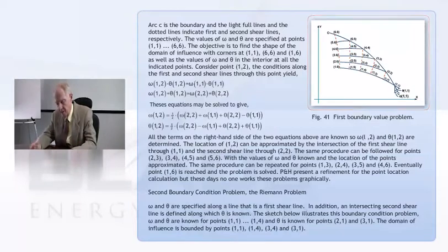And I could just keep going along that line and work out the points that are adjacent to the starting line. When I get those, now I have omega and theta at all those points. And I can then do it again with that second row of points. And I can keep going until I get to the point 1, 6. And then I'm stuck because Hencky's theorem won't do any more for me.